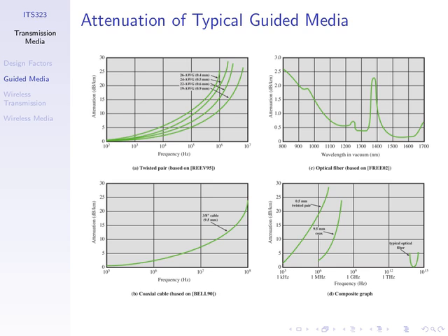All this shows, you can look at a later stage, it's not so important. It's just showing how much the signal attenuates. Signals attenuate at different frequencies at different levels. So for our coaxial cable, for example, remember our signal has many frequency components. The components with a low frequency have less attenuation than at a high frequency. So our signal actually is made up of multiple components. Maybe the main point here is that this is the attenuation at different frequencies. Twisted pair at the higher frequencies of 1 megahertz has a lot of attenuation.